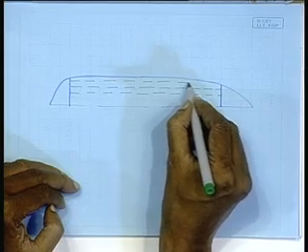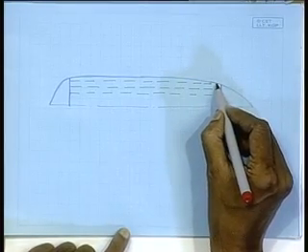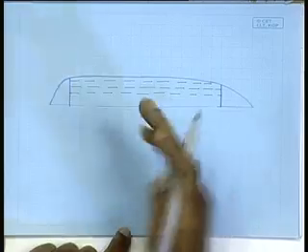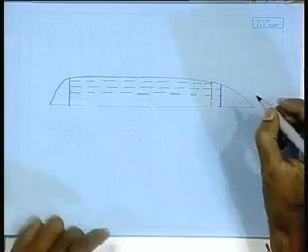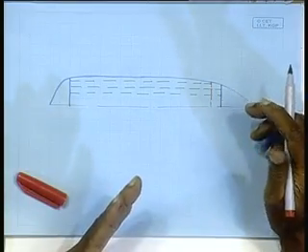So, you see these stiffeners as I am drawing, they are going very nicely. Only thing, the last one I have stopped there. The whole idea is, if I go further, it hits the shell. As I have said, you cannot terminate anywhere in the shell, just the end hanging. It has to be properly terminated in a transverse member. So, there is one of my transverse members, which is referred to as deck transverse, right? Deck transverse we will see while doing the midship sections. I have shown you some of it. One version of deck transverse is the hatch end beam. The same deck transverse, when it comes at the hatch end, we call it hatch end beam, right?